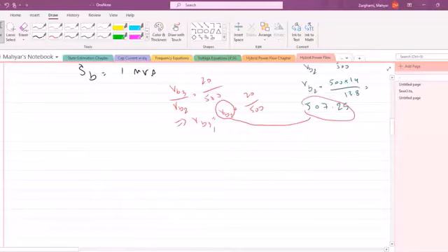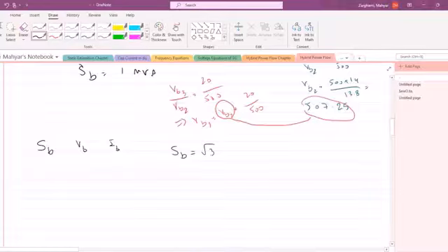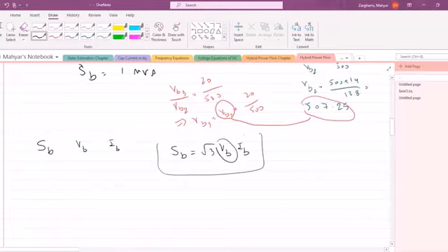And then, once you have the base of power and the base of voltage, you can find the base of every other type of quantity in your system, which includes current, for example. Current is one that we use a lot also. So what is the relationship between S base, V base, and I base? S base would be square root of 3 times V base times I base when you have a three-phase system. Usually in three-phase systems, you pick the base voltage to be the rated line-to-line voltage, and based on that, this relationship holds.